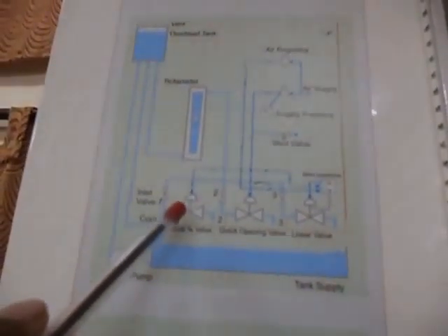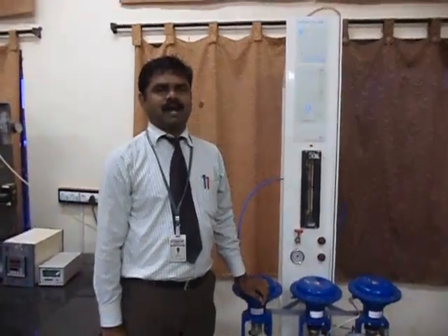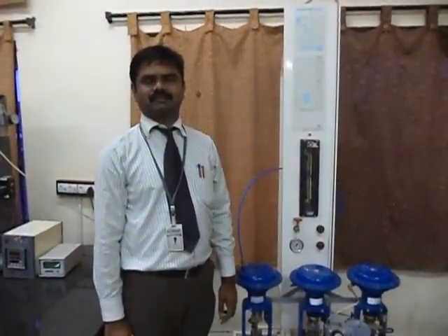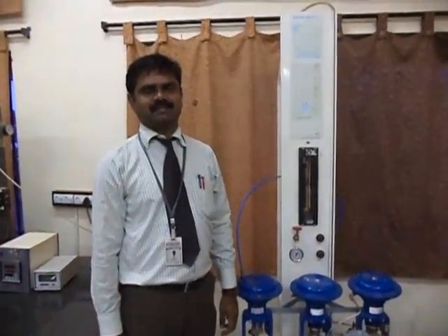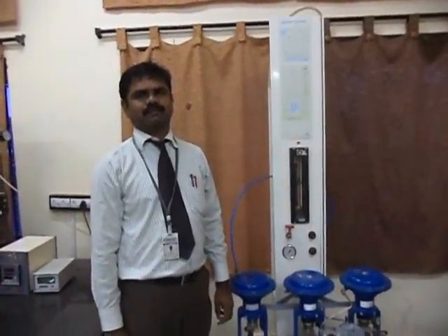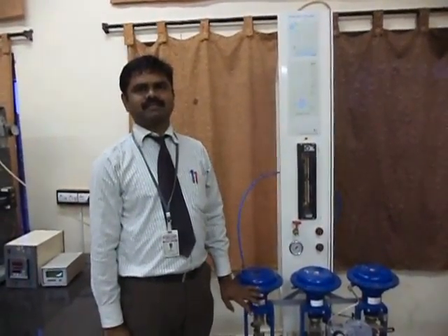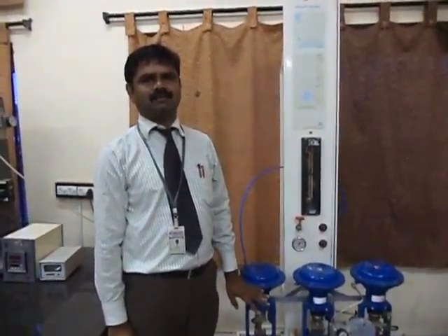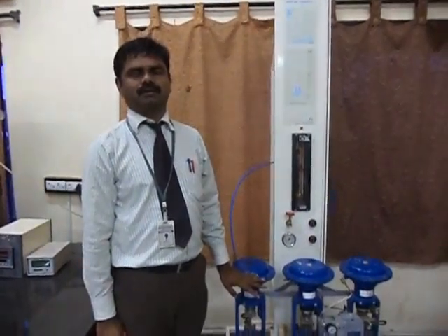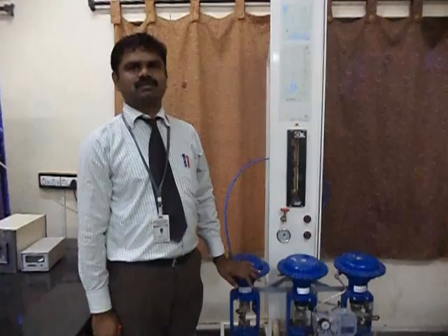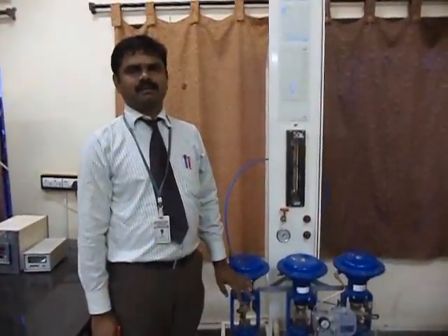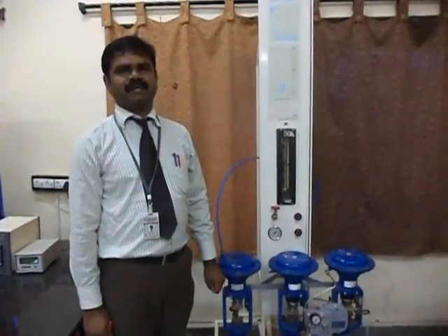There are 2 types of characteristics in the control valve, based on the relation between stem position and flow rate: inherent characteristics and installed characteristics. Inherent characteristics show the characteristics of the control valve, which are entirely related to stem position and flow rate. The flow rate of the liquid passing through the control valve is based on the control valve characteristics alone. Such a type of characteristics is called inherent characteristics.